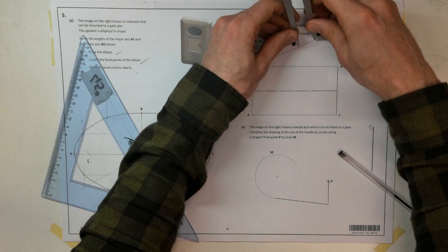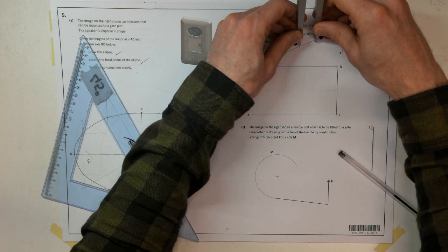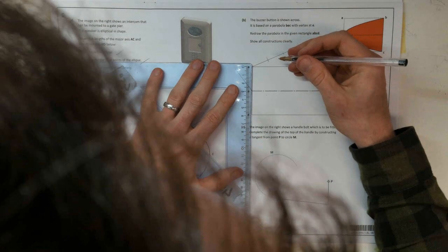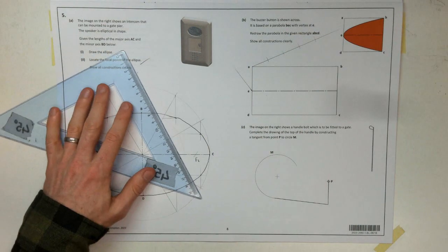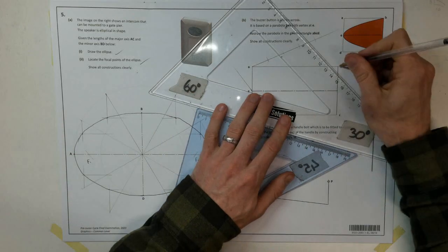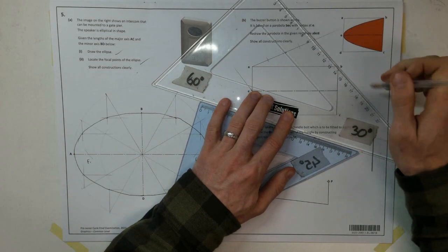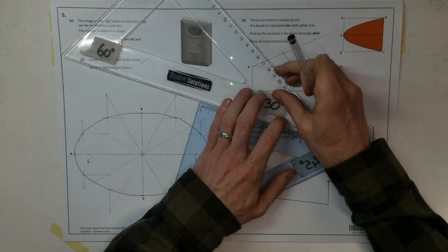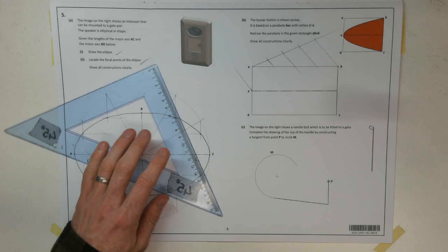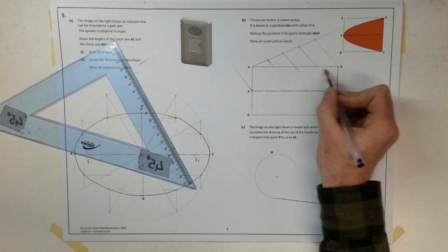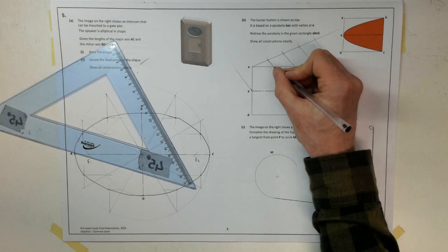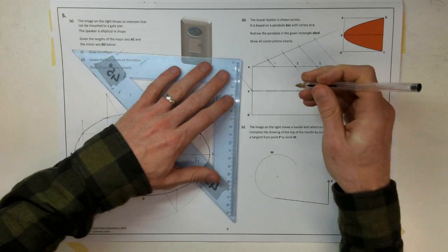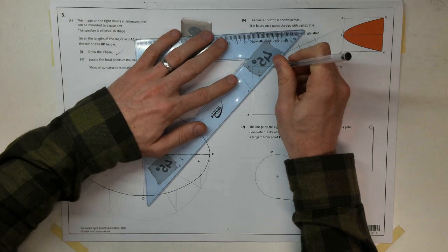Might even go forward. Yeah, just measure it. No, okay, that's not a visible line either. Okay, so slide and set squares then. Important line is from B to that line we found. Swing an arc, or draw parallel lines. Now this line here, that's parallel to our vertex. We're going to join each one of those, 1, 2, 3, back up to our vertex. They have to join to our vertex.